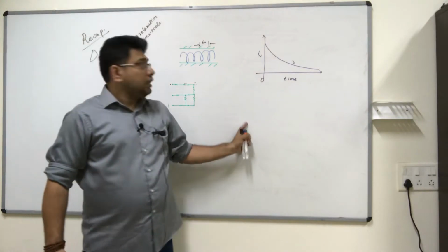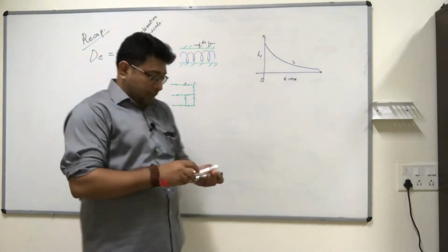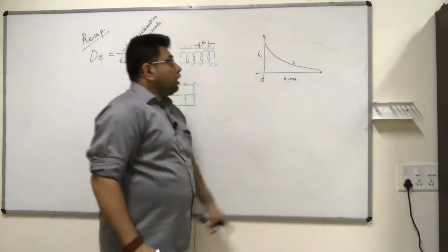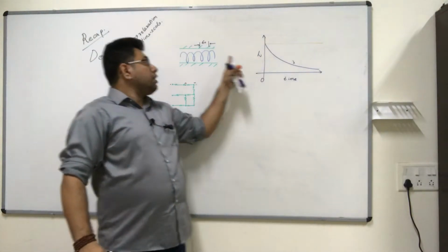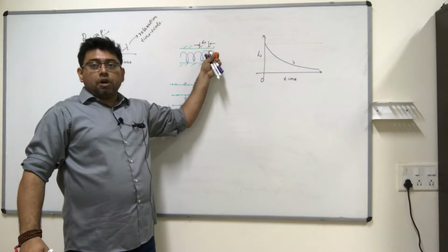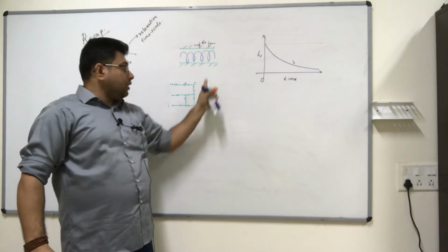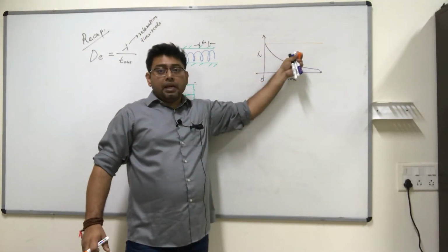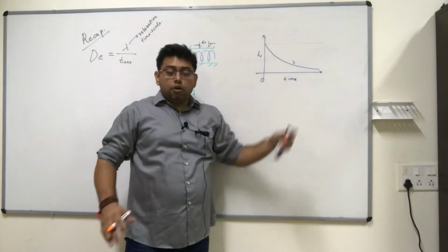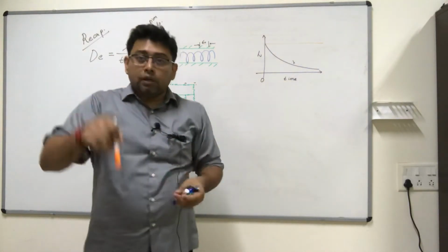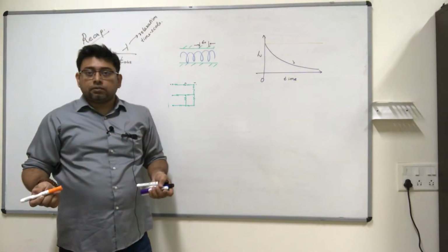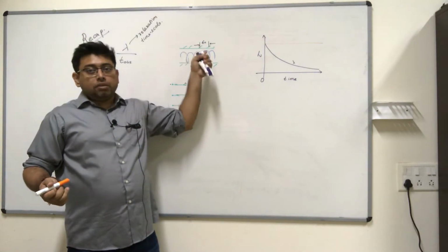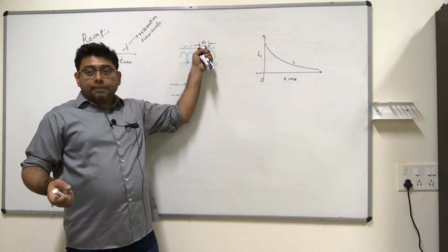So in a solid, this decrease of stress would never happen. Instead, you would get a straight line. You would have to keep a constant stress in order to keep this epsilon naught. Right? That's what a solid is. So in a solid body or a perfectly elastic body, there is no mechanism available at the molecular scale for the stress to relax. Because if the stress relaxes, then this epsilon naught goes back to zero. But that's not the purpose. You want to hold epsilon naught at epsilon naught.